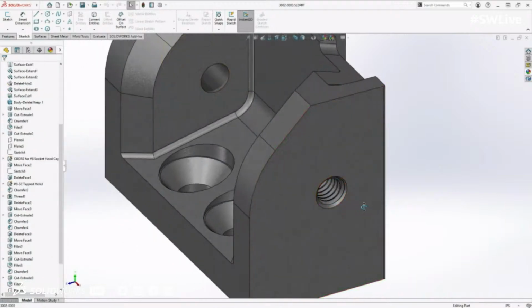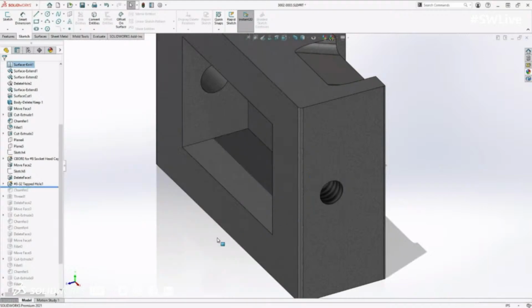If you're doing a 1/4-20 or smaller, I throw a 25 thousandths chamfer on there. And if I'm doing a 1/4-20 or bigger, I'll throw a 50 thou chamfer on there. And that's from me being a machinist back in the day. If I was going to tap a hole, I would always run a chamfer operation to put a chamfer for my tap to lead in so that I would have less risk of breaking a tap. But also when you go to run your fastener in there, it's just a smoother transition.